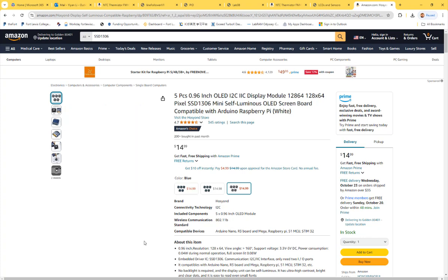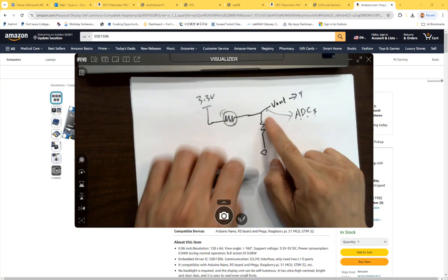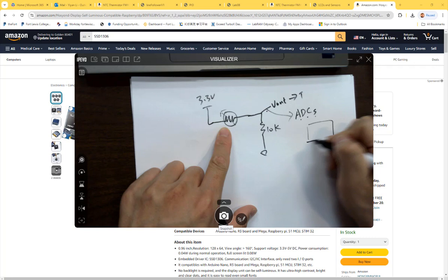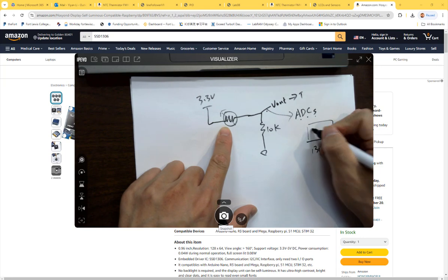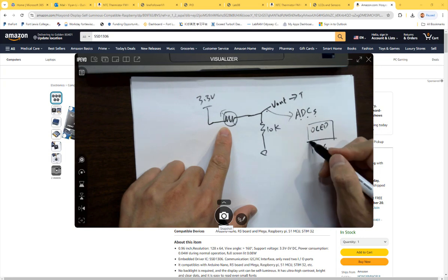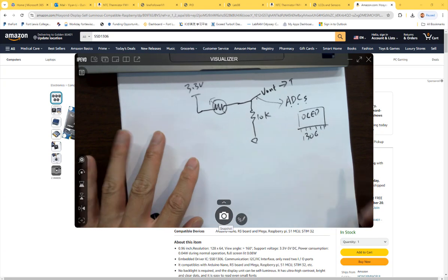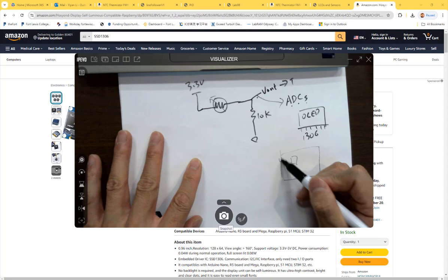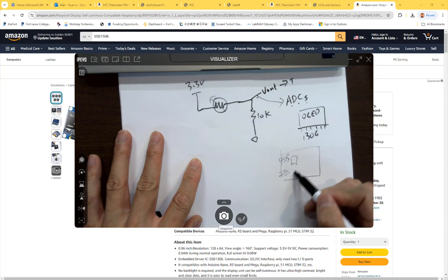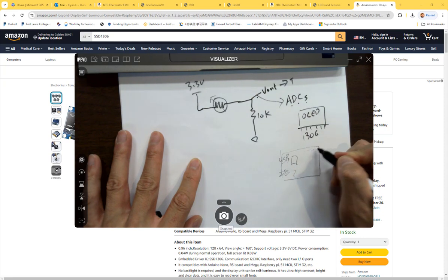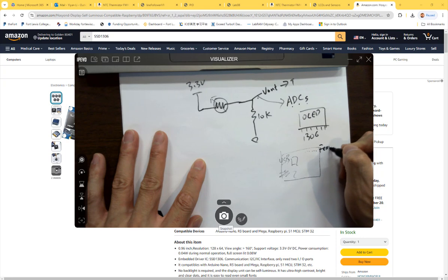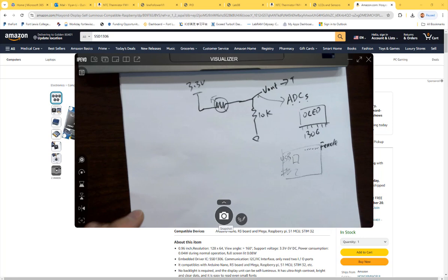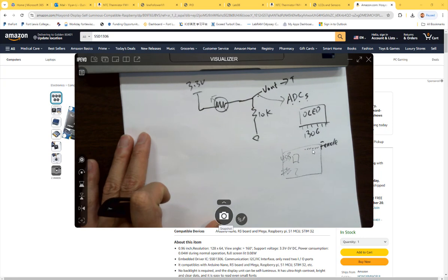So get a temperature sensed, okay, using this guy, the thermistor, and with the SSD1306 OLED display module. So what you want to do on the PCB board is, for example, here's a PCB, right? That's a microcontroller, that's a USB, whatever, okay? So there should be a female header pins, so you can directly insert this OLED display module to the header pins.